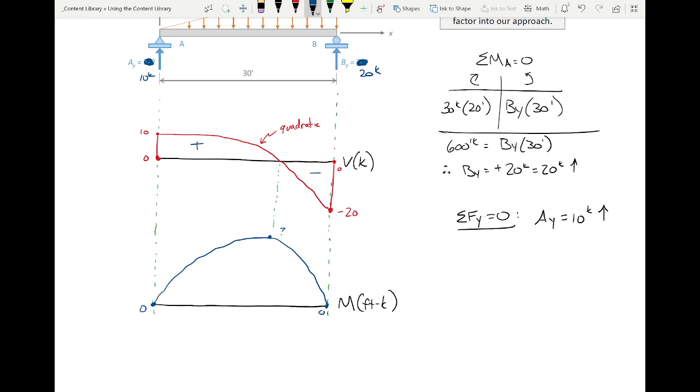And I know that some of you are probably thinking, wait, isn't that just 20 feet? No, it's not. Because it's not where the centroid of the triangle is. It's where the shear function equals 0. And those aren't necessarily in the same spot. It's close, but it's not quite. So there's a lot going on here that I don't know, right? Make sense? Everybody with me so far?